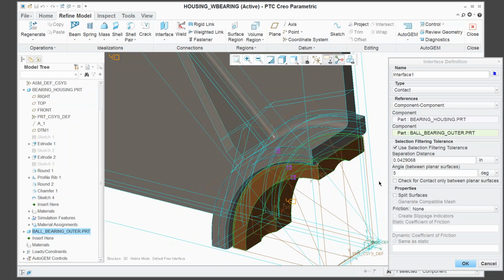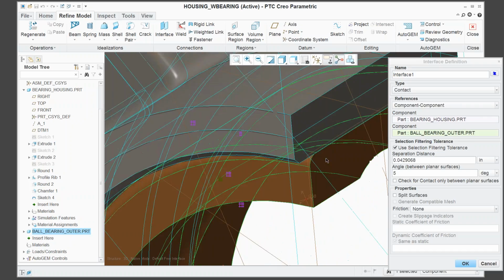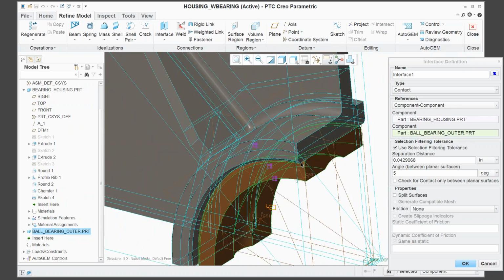This is simple enough we don't have to do it, and very importantly, by choosing component, it's going to pick up this fillet out here, which is actually a good thing. You don't really want contact surfaces with sharp edges. So that's actually going to help us. All right, our minimum distance here I'll say is 2,000. So anything that's closer than that is considered to be in contact. Now in fact they're in interference, but it's within that tolerance.